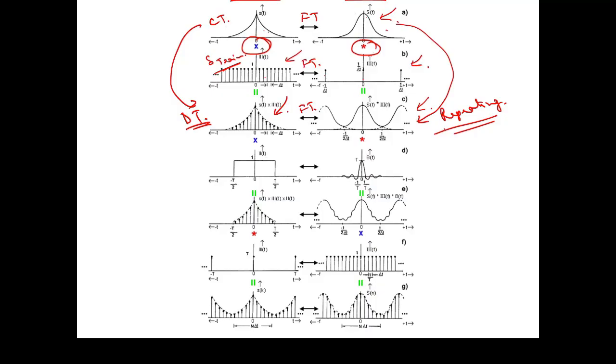Now since it is repeating itself, we have to take the continuous time signal which is band limited. Why? Because if you do not limit the band of frequency components, say for example 0 hertz to 100 hertz, then when it is repeating itself there would be overlapping.